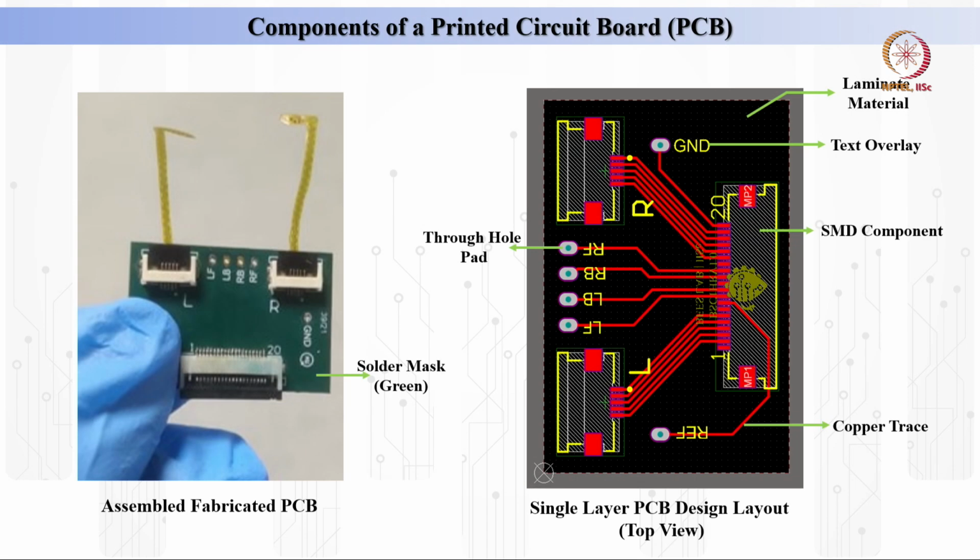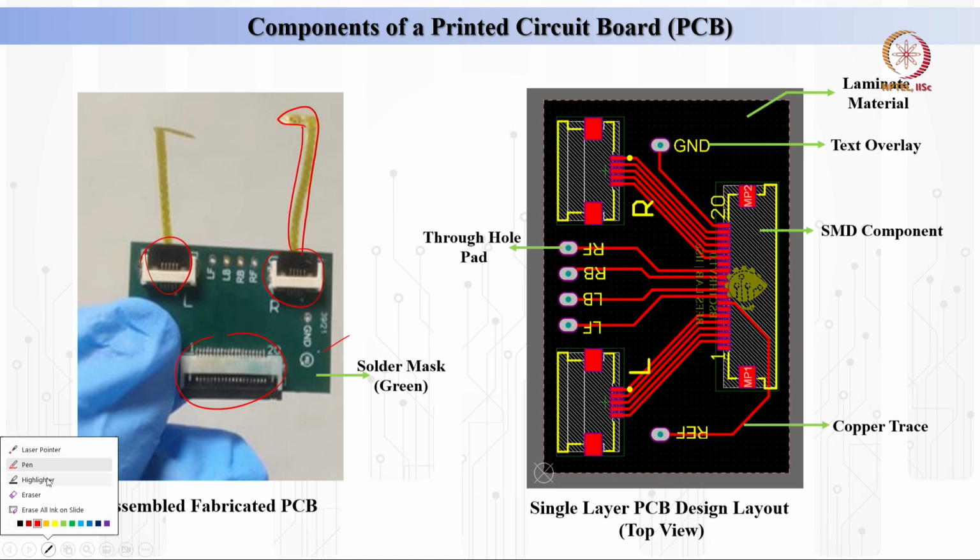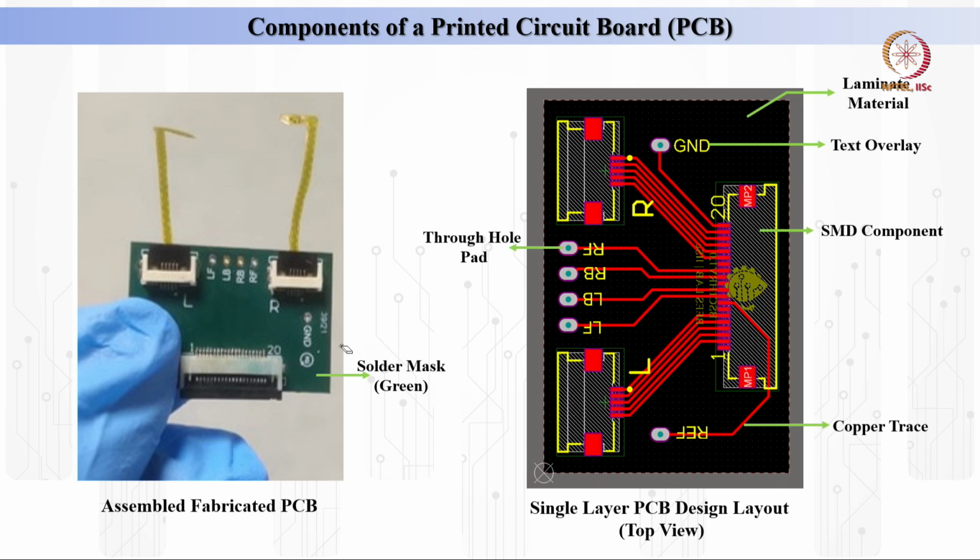So once you make the PCB, you send the Gerber files to the manufacturer, and you get a PCB that looks like this. This is just the interfacing PCB that we made, which is assembled with the components here on the top and the bottom in order to interface the sensors that we have fabricated. So this is a neural acquisition sensor that can be placed on the scalp or on the skull in order to receive EEG or ECG or ECoG signals.